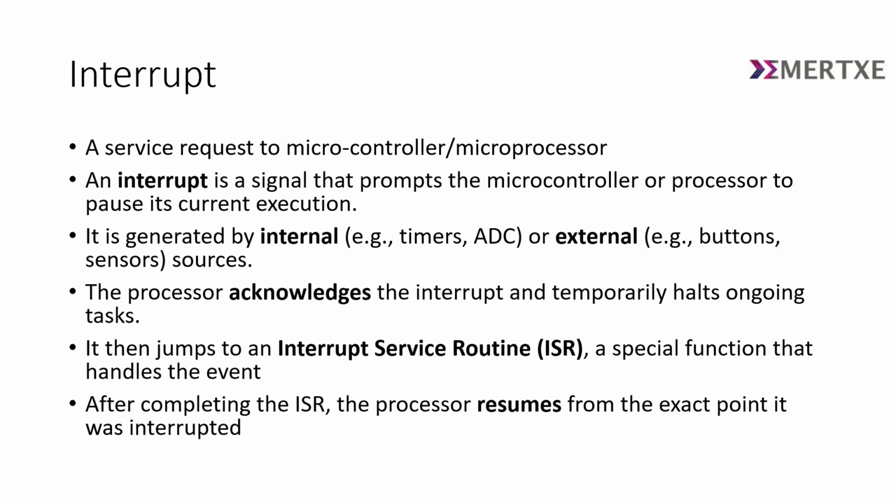Next is an interrupt. An interrupt is nothing but a service request to a microcontroller or microprocessor. An interrupt is a signal that prompts the microcontroller or processor to pause its current execution. It is generated by internal sources like timers or ADC, or external sources like buttons and sensors.